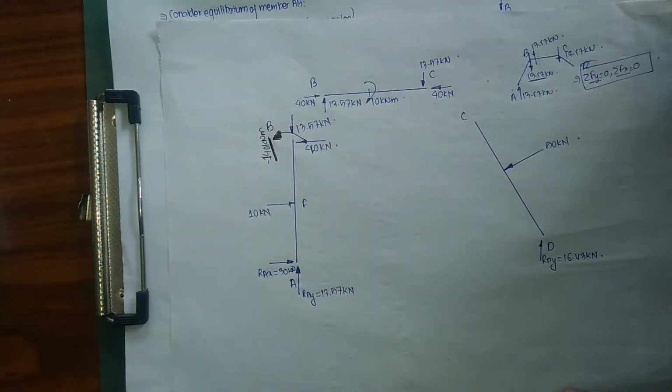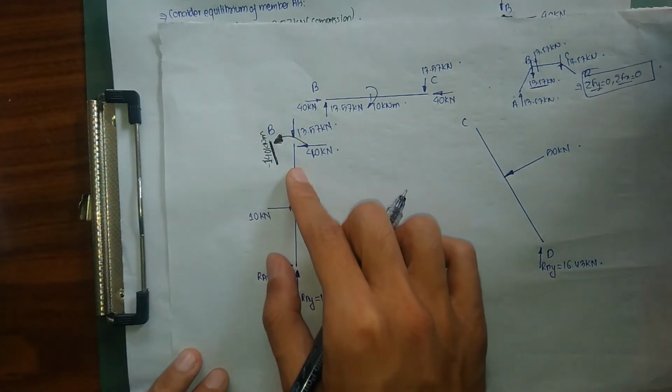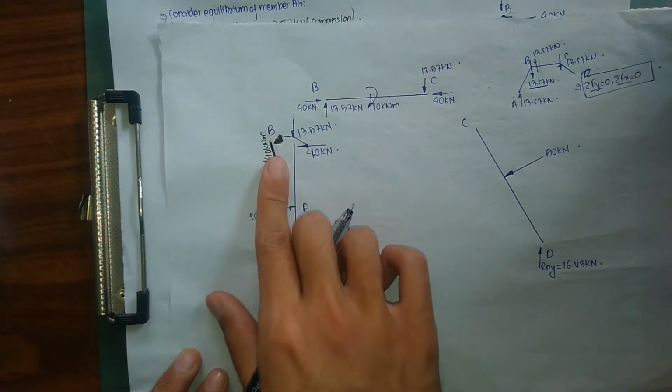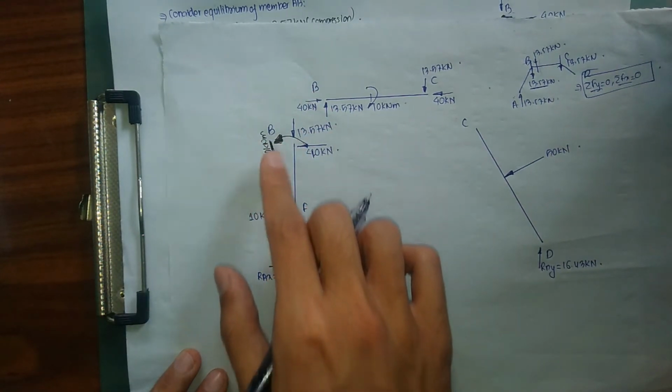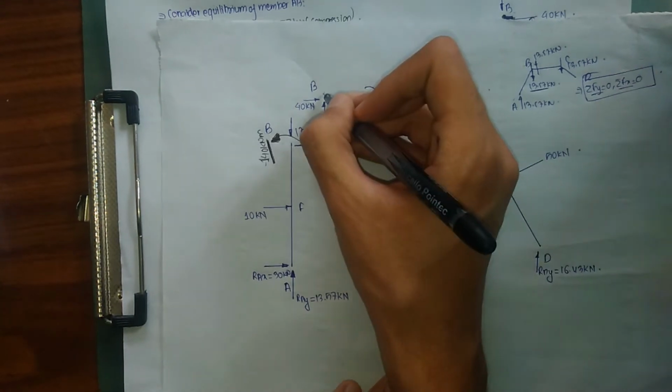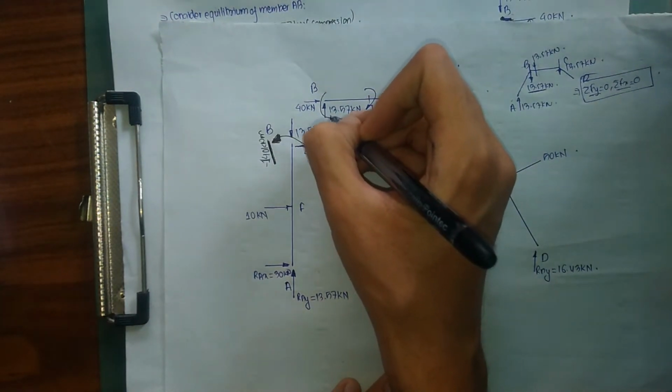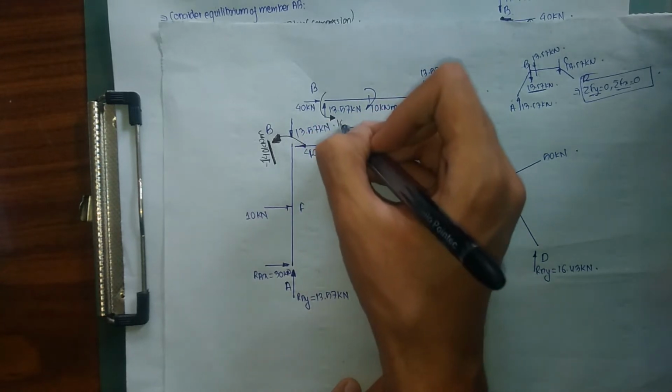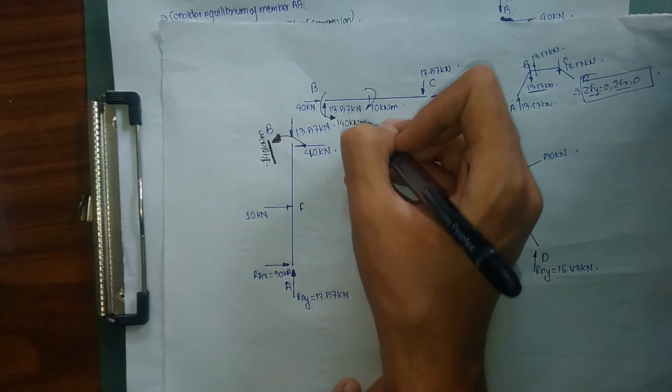Since our joint transfers our bending moment, we are going to have our anti-clockwise moment of 140 kN meter at our point B as well. So let me write it down in this way, minus 140 kN meter anti-clockwise bending moment.